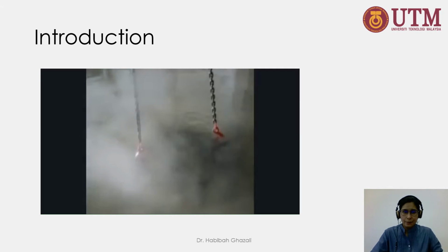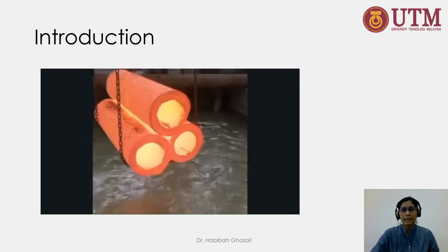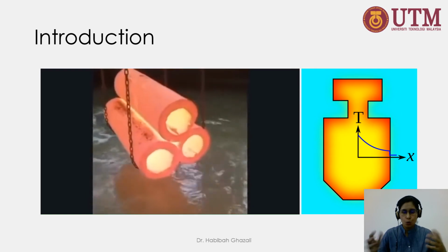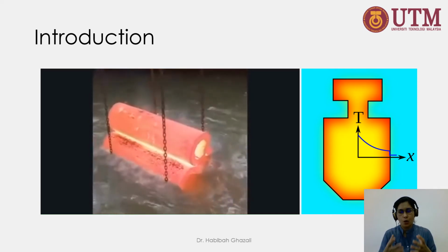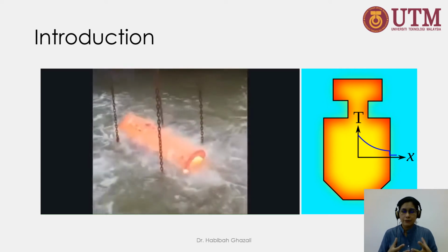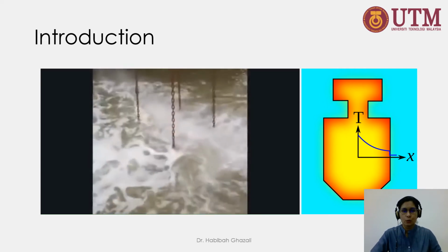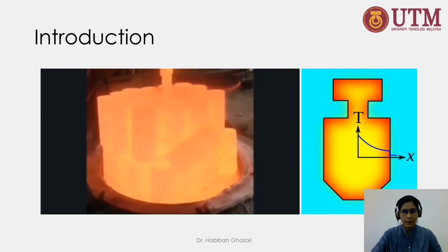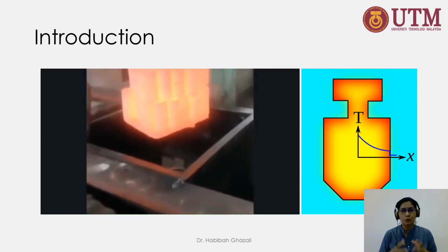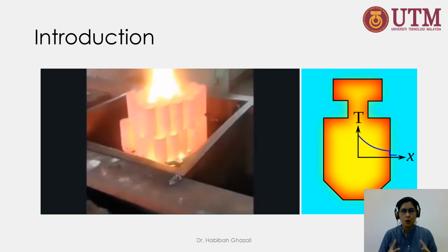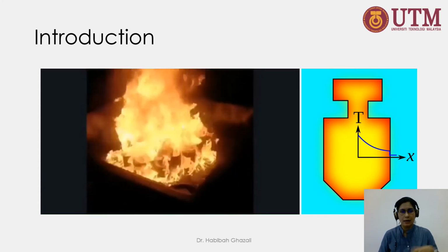Obviously, when this hot steel workpiece is being cooled, the area in contact with water will immediately cool down to the temperature of the water itself. However, the inner depth of the material will not cool so rapidly. And in a workpiece that is so large, the cooling rate may be slow enough to allow the austenite to transform fully into other structures other than martensite.